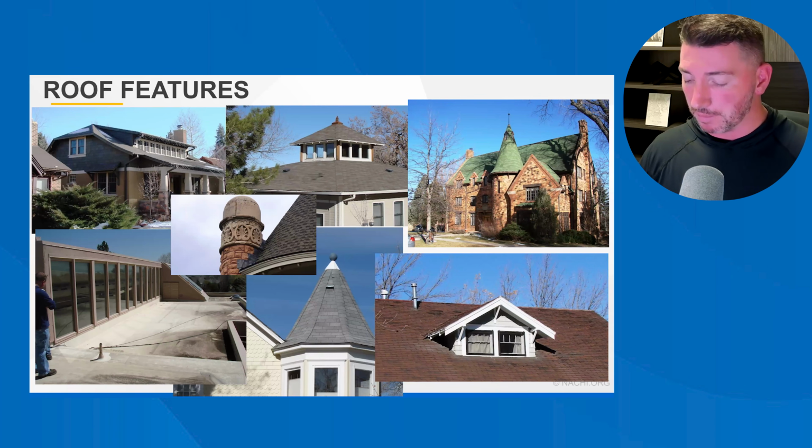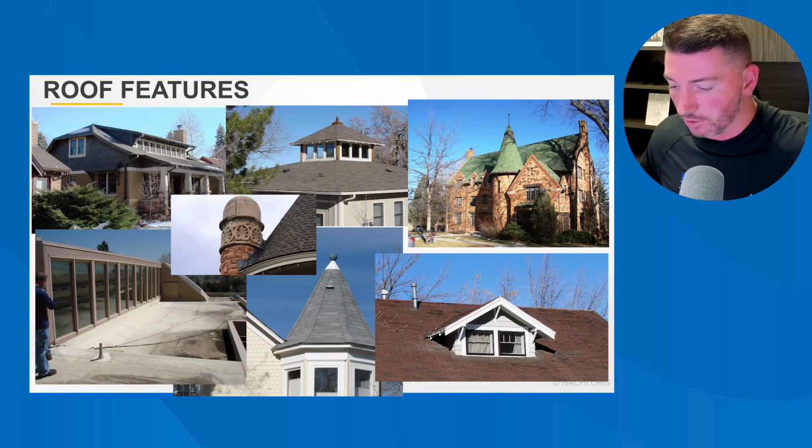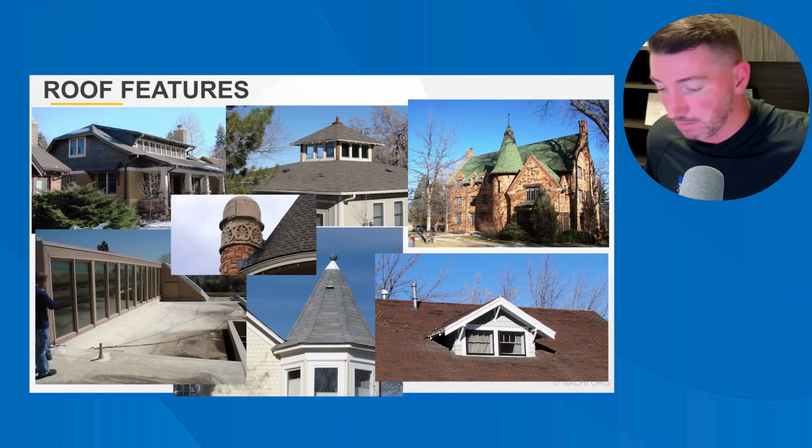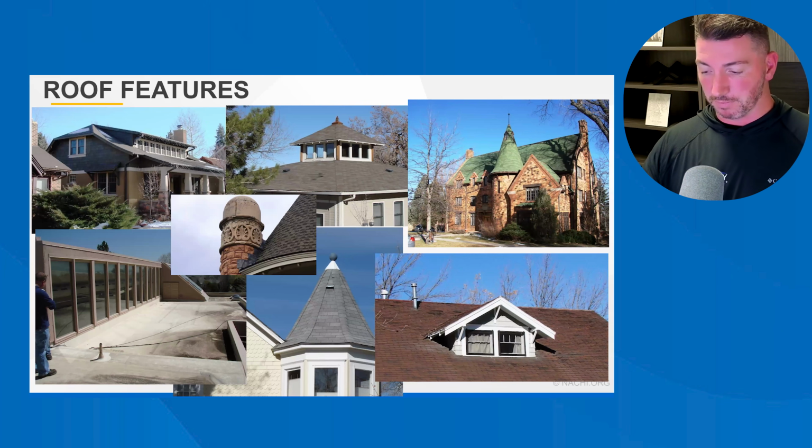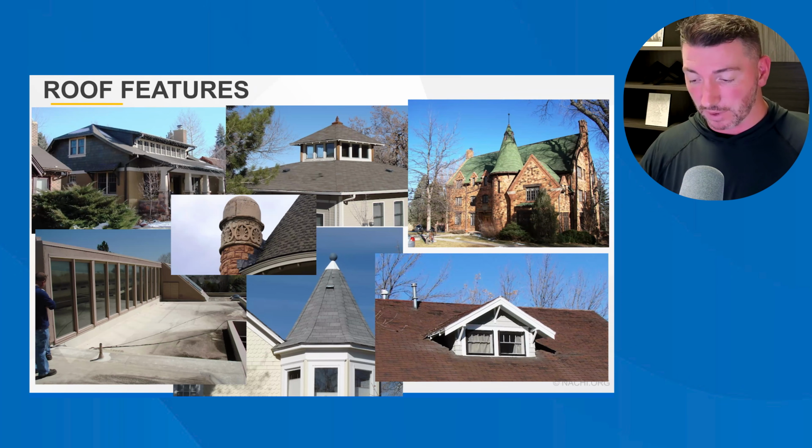So the debris buildup behind those conical roofs intersecting with the main roof structures can be pretty significant. That debris holds moisture against the roof and the flashing, which often corrodes the flashing more quickly than it would on the rest of the roof. So those areas are a weak point. And if you can't confirm the condition of the roofing on the back side of a conical roof, you need to disclaim it and recommend inspection by a qualified roofing contractor.